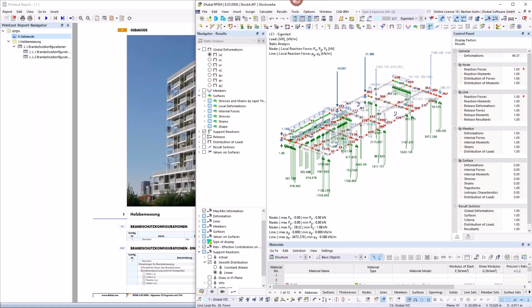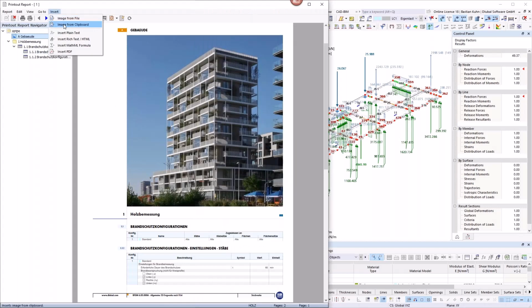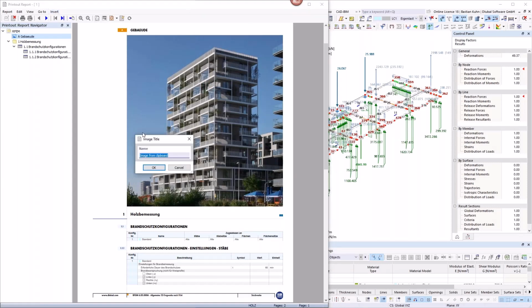Okay, so let's say we have this story 4, and once again, this is connected to story 5, 6, 7, 8, to all the other stories in here. And this is something I want to print to the clipboard. And then when I go into the printout report from the model where I'm working on, I can say, okay, this is from story 4, say okay, and have it imported.